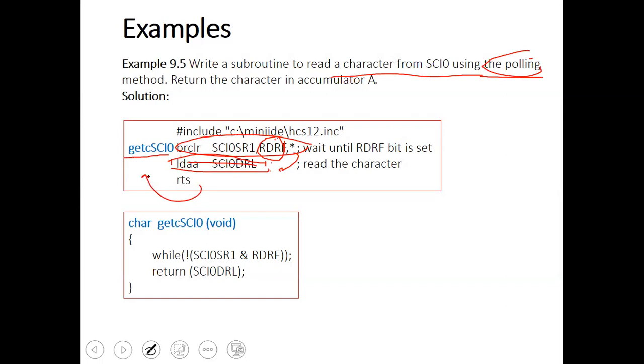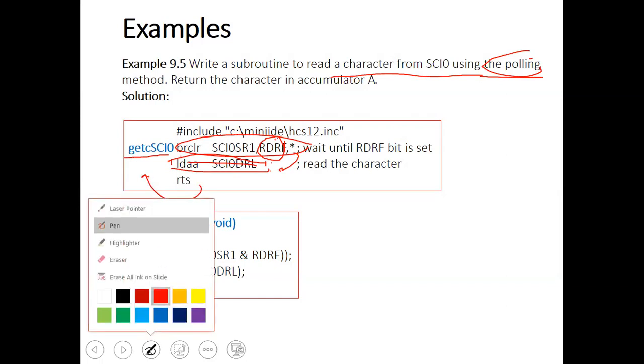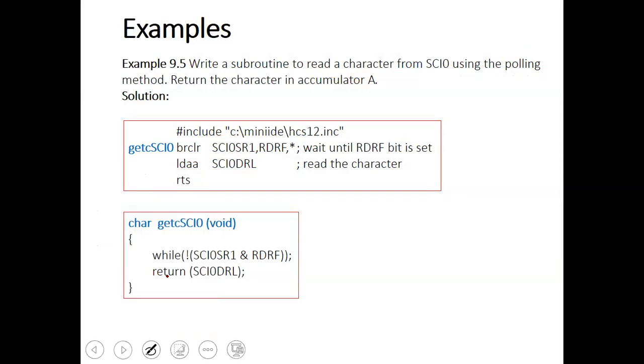And if we are using 9-bit mode, whether it is for parity or for data, then we need to read 2 registers, the low register and the high register, in order to read the 9 bits. But from the high register, remember, we need only 1 bit of data, which is the most significant bit in case we are receiving data. Go back to the breakdown of the bits inside the data registers.